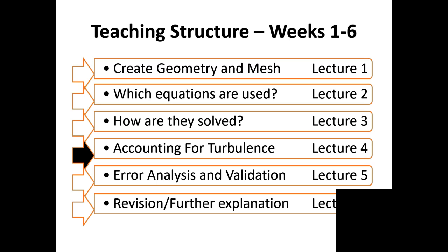Then you are supposed to do the T-Junction. Make sure that you have a good grid with enough grid resolution at the walls and at the bend, as well as at the junction. Some asked whether you need to change the fluid. It's okay to change the fluid. You can compare a couple of fluids if you want, but make sure that you do your basics right. Just simulate both with either air or water or the fluid of your choice.